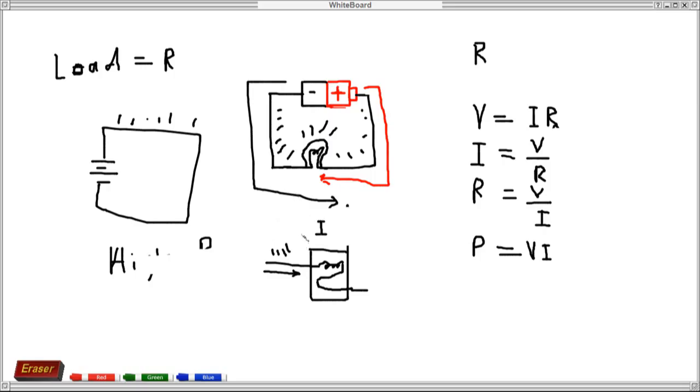Once it reaches that amount, the electromagnet is strong enough to break the circuit and cut it, and that's when your power goes off. It's a safety feature, because if it was directly connected without a breaker, your power line would start to heat up, melt the insulator and catch things on fire.